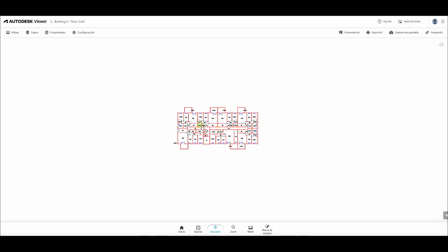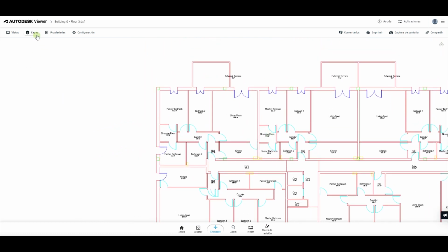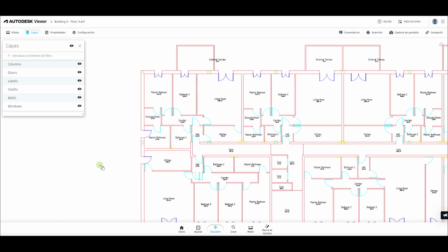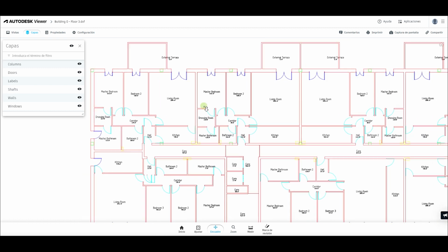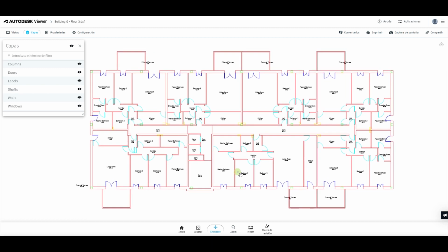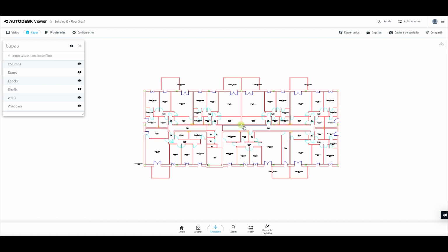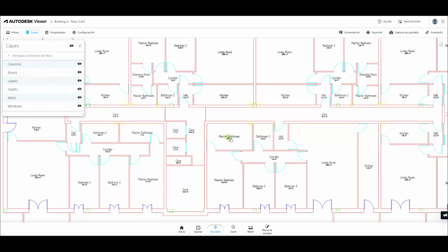In the CAD document download, a DXF file is generated for each floor of each building, for each basement floor in the project, and a general plan corresponding to the ground floor. All CAD files maintain the same layer organization, focusing mainly on the elements that make up the project. In this way, we can find a specific layer for walls, windows, doors, pillars, ducts, and projection. In addition to these layers, we also have a label layer, where we will have text with the type of space and its area.